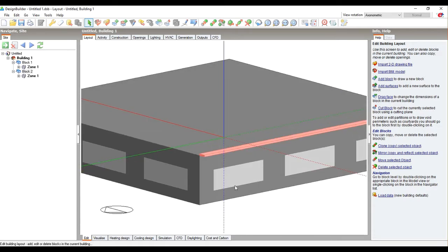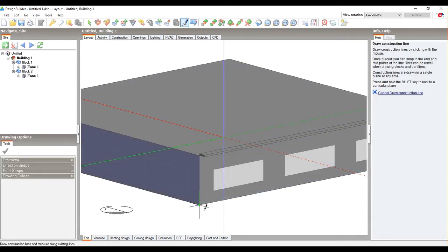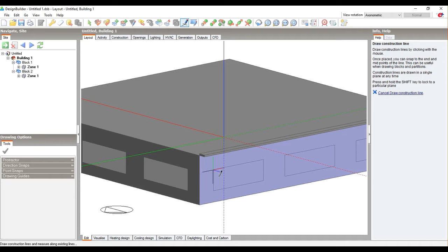Now if we click the component, we can put it at any height we want. So first we can create the height we need. Let's say that we want to put it just above the window, so it's almost 2.35 meter high.